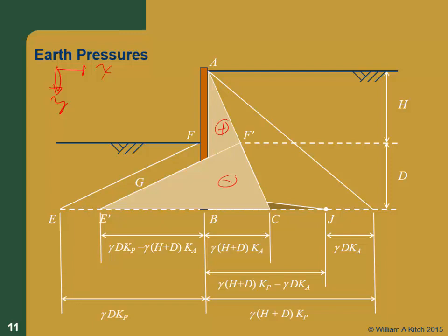So now what I'm left with is negative stresses. I've eliminated this part of that triangle, but now I have negative stresses over here. This part here will actually be 0 now. And so I'm going to add in this one positive back, and that'll leave me the net of this plus this plus this. So that'll be the net earth pressure I have when I'm done. Did you follow that? Yes, no, maybe so.